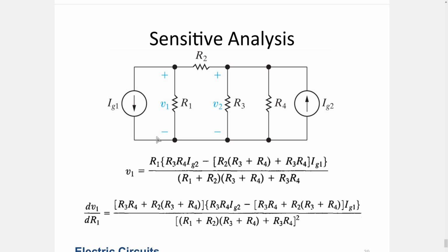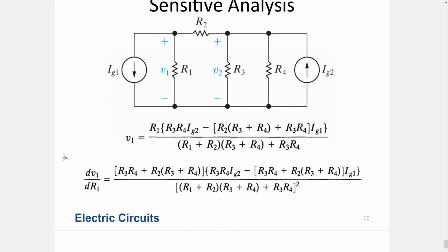So you want to make sure that your circuit performs under every condition as intended. You want to see the performance boundaries, and we do this by making Monte Carlo corner case simulations. This is why at the very beginning, when we were dealing with LTspice, I tried to give you a glimpse of it. Maybe it didn't make sense at that time, but I think it makes more sense at this point. This will be the last topic to discuss for today's class.